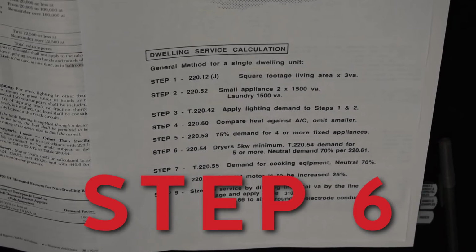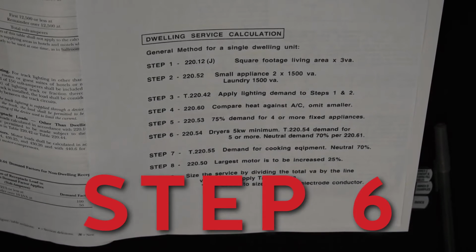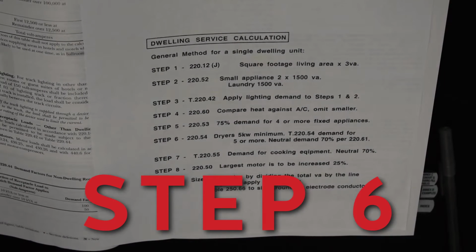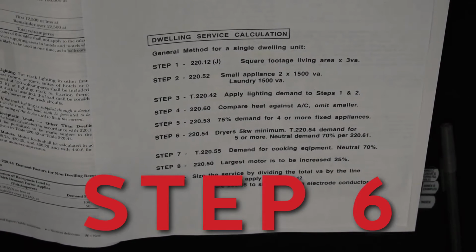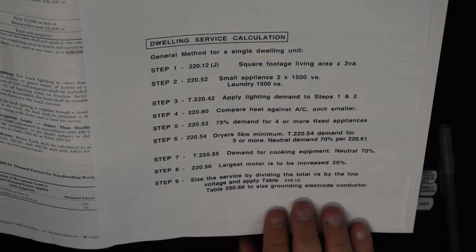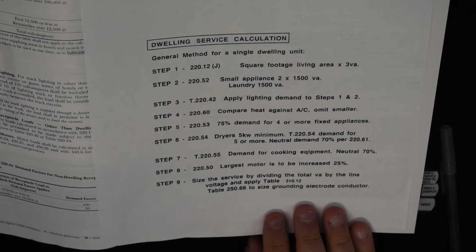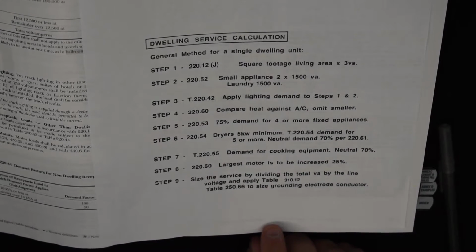Now let's go to step number 6. Step number 6 takes us to 220.54, and it says dryers 5 kW minimum, and it says table 220.54 demand for 5 or more. Well, if we're talking about a single family dwelling unit, we're not going to have 5 dryers, right? That'd be more for a multi-family dwelling unit or some type of apartment complex. It says specifically here that neutral demand is 70%. So far, everything we've been talking about has been a demand on these steps. But for a dryer, you get to take 70% of the total load specific to the neutral conductor only.